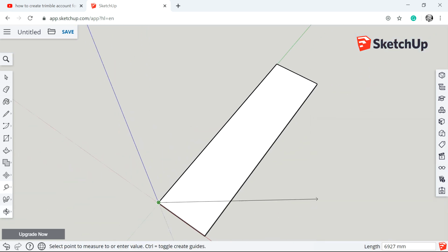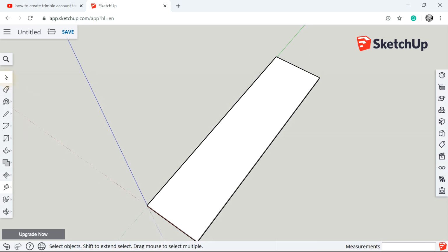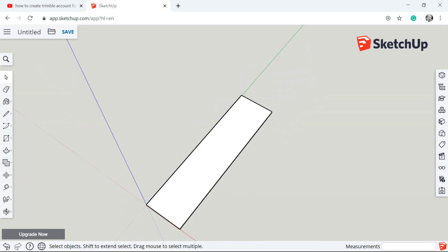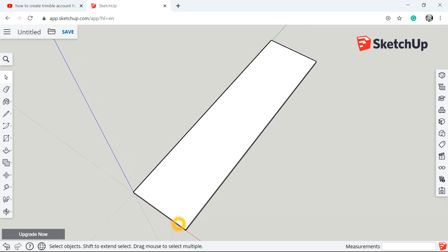Now when we start with our floor plan, you have to leave a bit of space for your walls. So what I normally would suggest you guys do is just take the rectangle tool, put it on there and draw just the outline of a wall there. So you'll go 10,000 comma 100 and then enter. So that's just giving me an outline of the wall. So I'll go here as well, and then I'll go 2500 comma 100, enter, and then I'll do the same here.